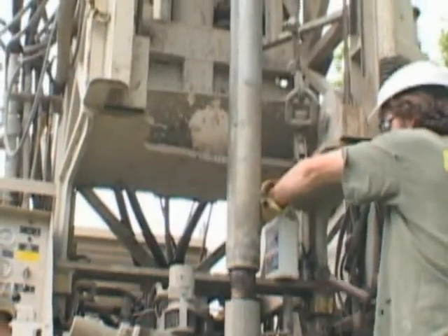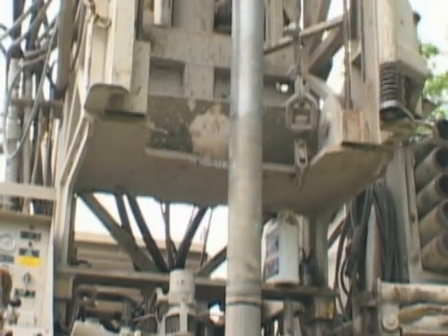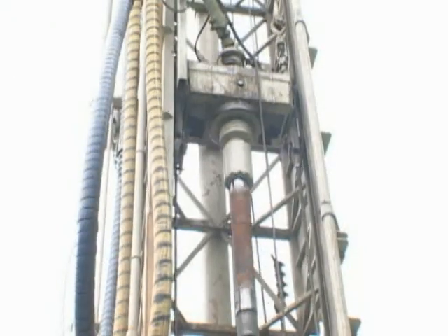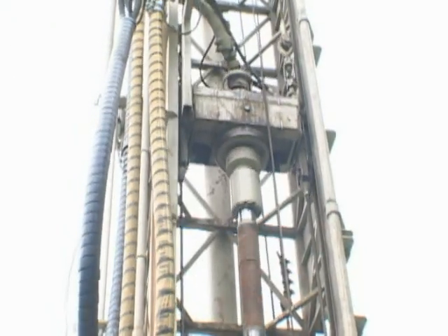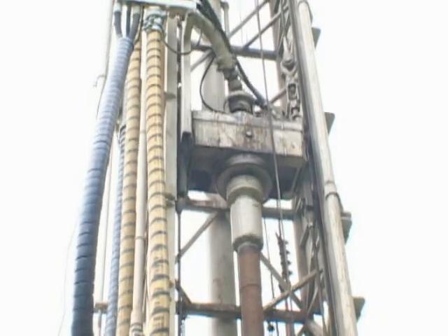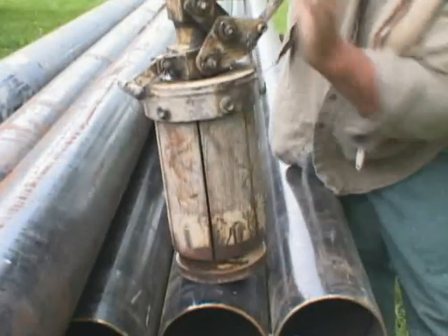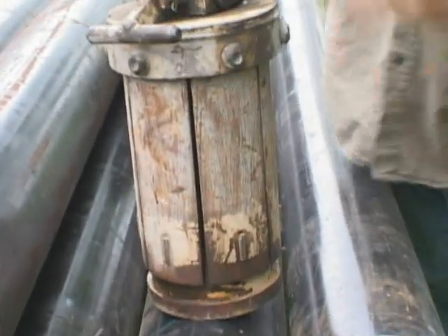In identifying the aquifers, care is taken to record the depth and extent of the aquifer, as well as to ensure proper slot size required for screen installation. Drilling speeds vary widely depending on geology and hole diameter. The oversized hole is temporarily stabilized with the drilling mud. Casing installation usually occurs in 20-foot sections.